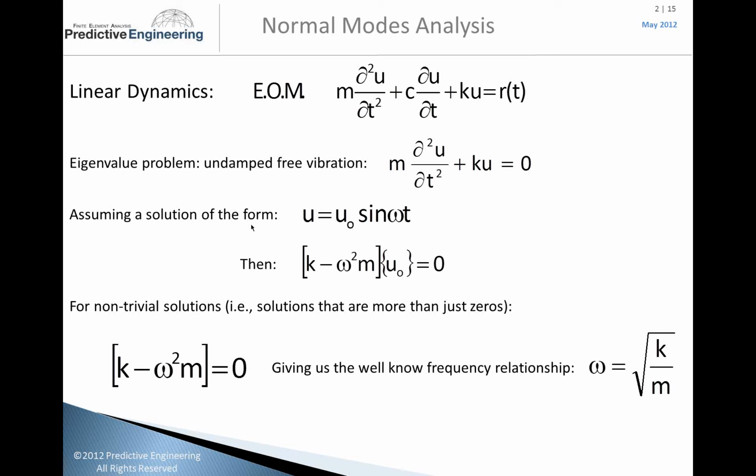These are the fundamental equations, and it can be a wonderful guide. It tells you a lot. It tells you the frequency is proportional to stiffness over the mass. And these are little things people always talk about quickly: just increase the stiffness, or conversely lower the mass, to raise the frequency of a structure. This is where it all derives from. Real simple.